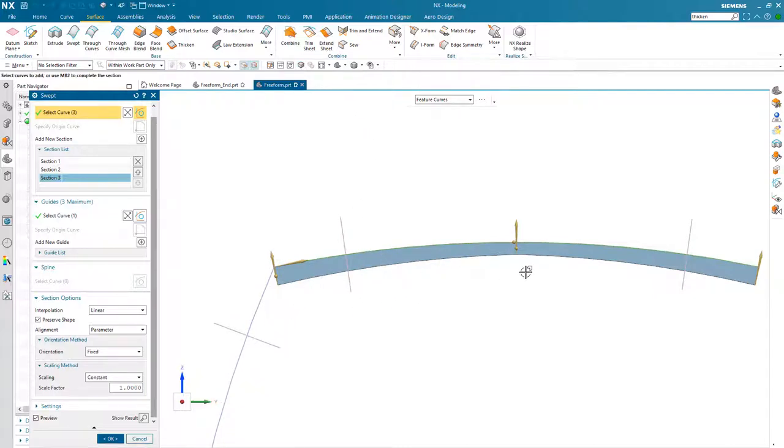Now if you take a look, you see that our current interpolation is linear. There are two other types of interpolation: we can do cubic, we can do blend, and as I change to each one of those, you notice that it will come in and then smooth out, whereas the previous option, linear, basically takes that cross section, no matter what that shape is, comes up and stops and then mimics that cross section, and then from there goes on to the next one.